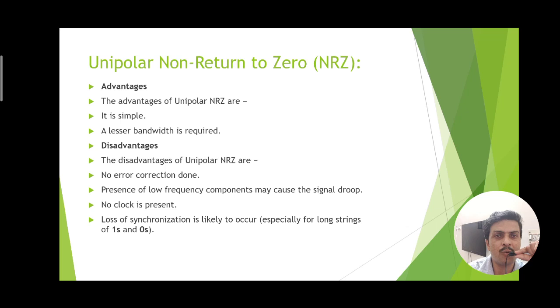Presence of a low frequency component may cause the signal to drop. No clock pulse is present. Loss of synchronization is likely to occur when there is a long string of ones or zeros.